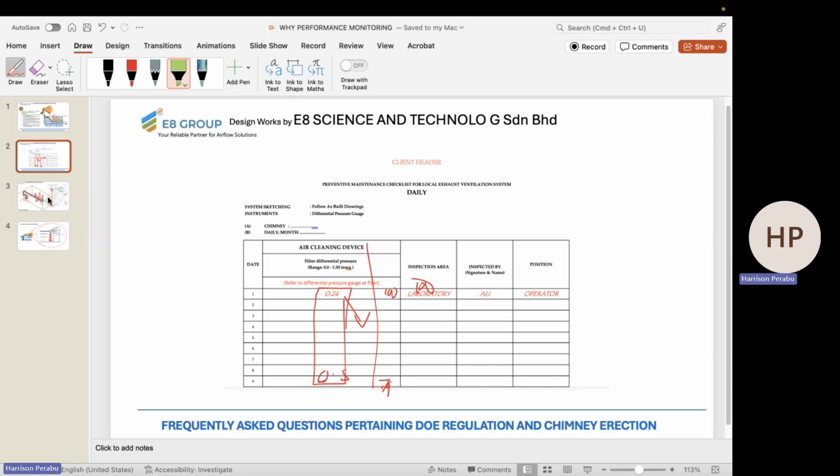If you don't have an anemometer, you can start off by having about 0.4, so 0.5-inch water gauge, and take note of the system. If you have a smoke test kit, you can do a smoke test and see whether there is a tremendous drop. But do engage with a third party on a periodic basis to record these two data. Preventive maintenance is an ongoing data acquisition exercise, and you could understand the system better and implement better.